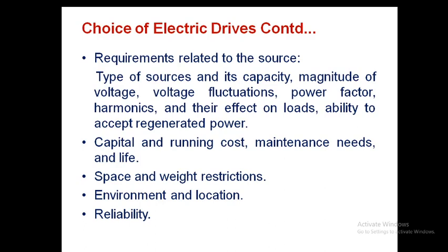Environment and location. In a few drives, explosive environments will be there, radioactive environments will be there, where a few drives will give some sparking, which we can avoid. And the location, where you are keeping the electric drive, like on the top of a turbine, a wind tower, or submerged. So that location also matters while choosing the electric drive.